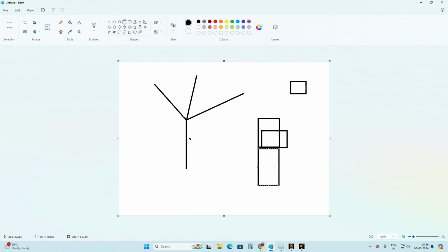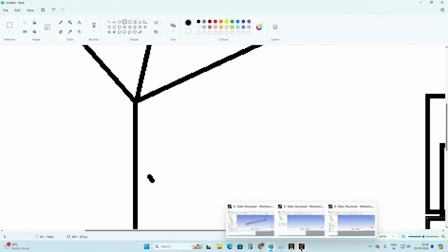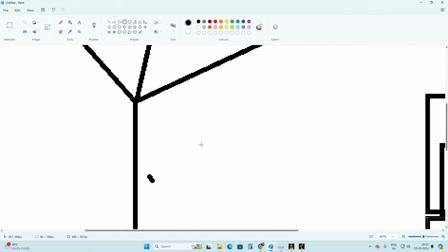At this joint, the cross sections will be connected towards these things, right? It will be messy at this joint itself. If you click closer over this, you can see that a lot of joints are present here. It's kind of messy. So for this type of thing in software, what you have to do is an end release. Or while creating a 3D structure itself, nowadays the Ansys program automatically calculates the end release.